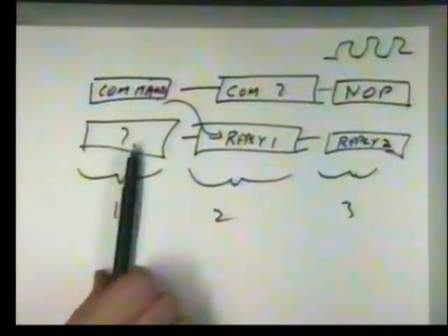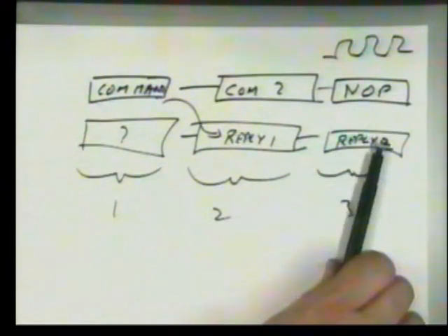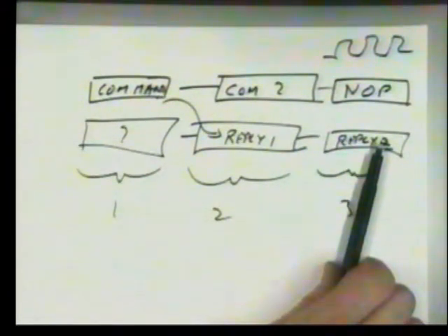Clock out a command, you get the reply back on the next byte cycle. Clock out a next command, then you get the reply. But in order to get this reply, something else has got to be clocked out. So you have to clock out some garbage. So there's some redundancy in this concept. If you've got a lot of data to transmit, then it becomes reasonably efficient. But if it's very small patchy bits of data, because of all this redundancy, the fact that the first command, there's always garbage back, and then we have to clock out in some form of no operation just to get the final reply back, then you have redundancy in the system, wasted bandwidth.